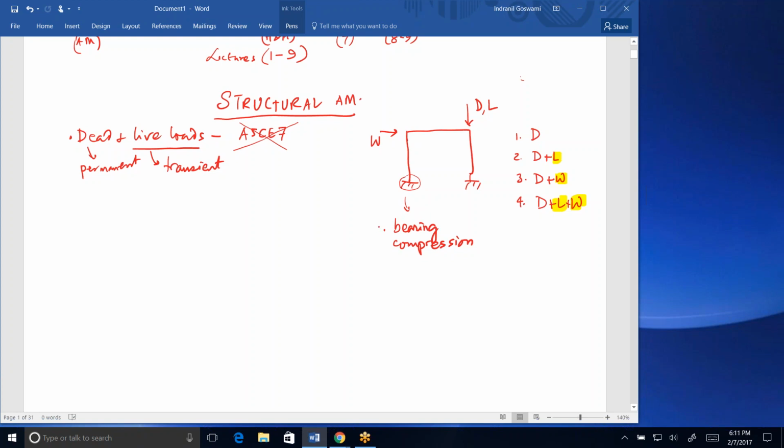So you could design this particular footing for bearing compression, the bearing capacity of that soil, or you could also design it for the unlikely but possible situation of uplift, if these loads causing uplift are going to be very strong. Now you notice that the wind load definitely causes uplift at this footing and causes bearing on the far side footing. And typically for wind loads, you'll design the structure for a reversible wind load, meaning that it could also go the other way, right to left, in which case the scenario would reverse: uplift on the right and added compression on the left.